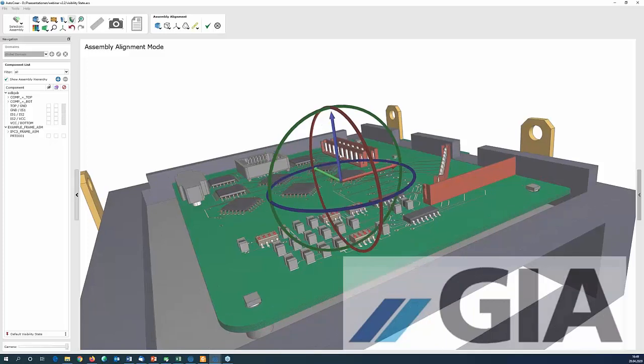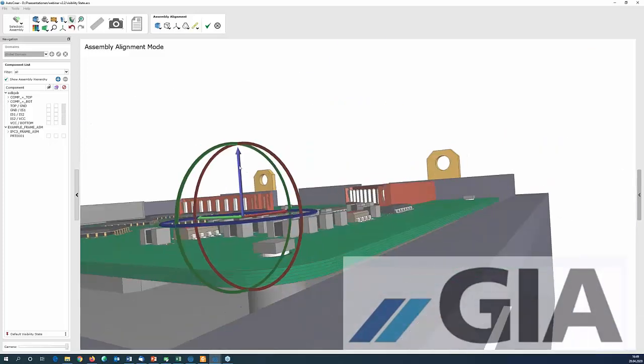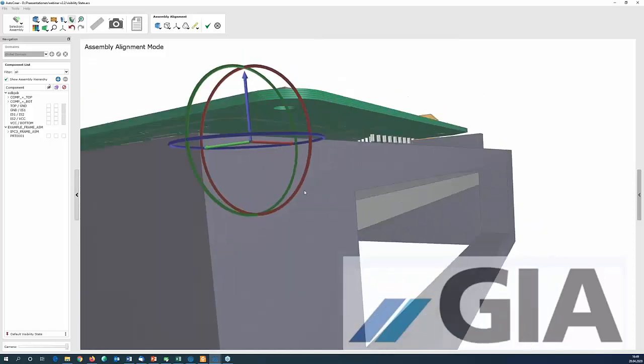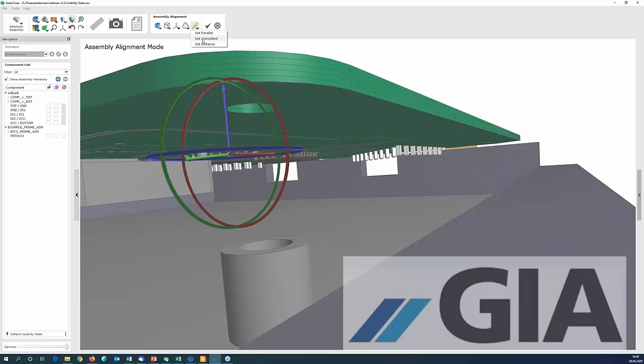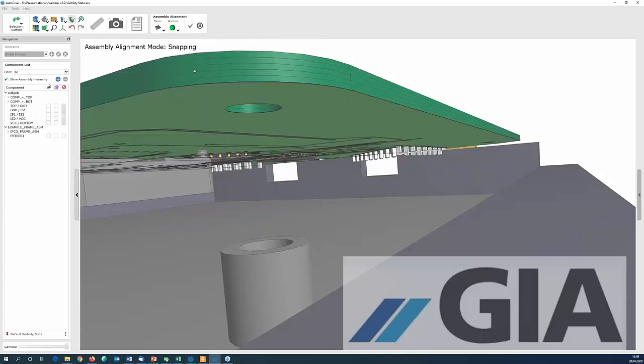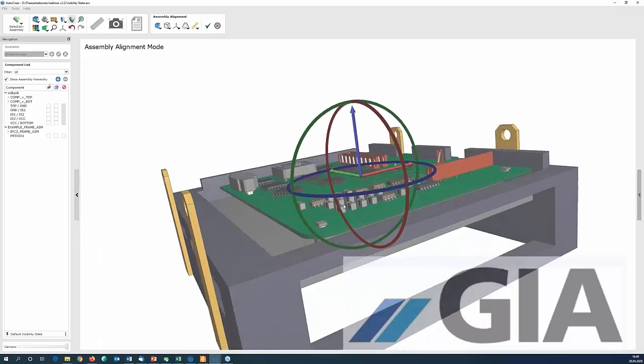Then, of course, you have to take care which operations you perform afterwards, not to spoil this snapping. But now you could, for example, say, now I want that this planar surface here on the bottom matches this one here, and by this you can also make exact positionings with these simple snapping functions.